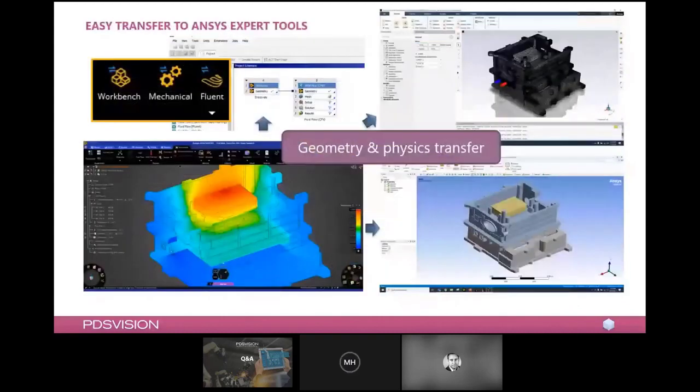If we keep highlighting these things, when you are doing something in Ansys Discovery, you have buttons to push the geometry or the predefined simulations to either Ansys Workbench, Ansys Mechanical or Fluent. In the background here, we can see the Workbench user interface where we have pushed the Ansys Discovery geometry, connected it to a Fluid Flow system, and there we can go for setup and go instantly to Fluent, should we have the license for that one.